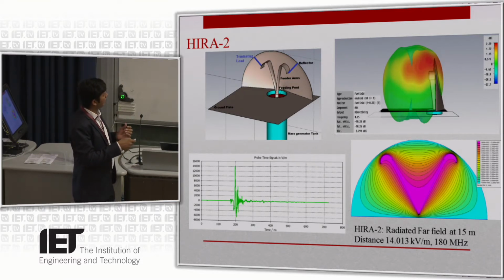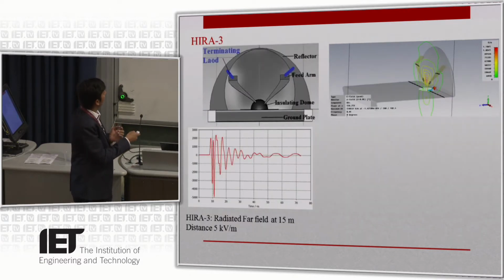This improvement is mainly because of this folded feed nature, and there is also a launching angle, called beta. This launching angle is very important, because we are launching, feeding the pulse to the arm and terminating it to a matched load termination. It's about 180 ohm. That's why the arm nature is there, and the uniform field distribution, called field factor, we improved by a 1.2 factor. So it is directly affecting the electric field intensity, about 14.4 kV. This is the improved electric field intensity.